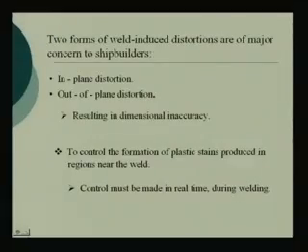Whereas buckling and angular are out of plane, and warping we have not mentioned. The whole structure buckles, angular, all together, it rotates. But primarily those are the 4 deformation types. It can be a combination, 2-3 things happening together, which may result in some other type of shape. So, all these result in dimensional inaccuracy, what I was already talking about.